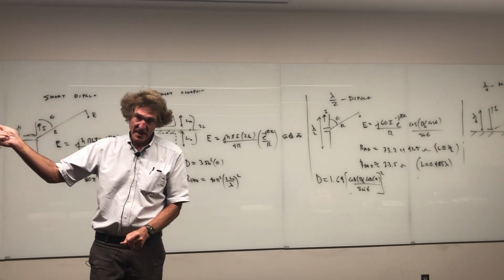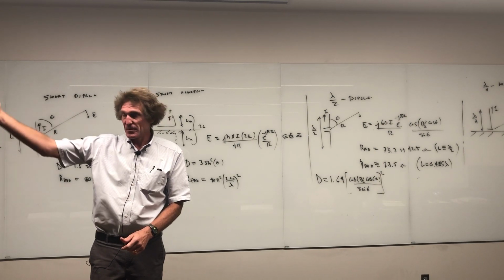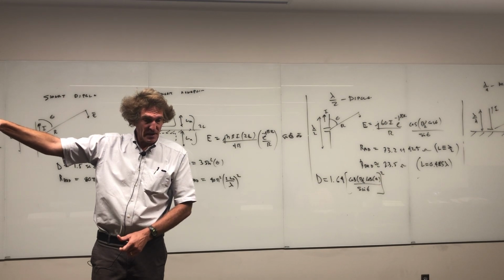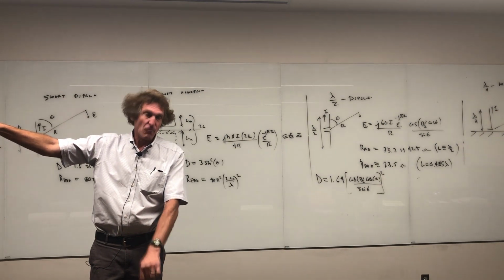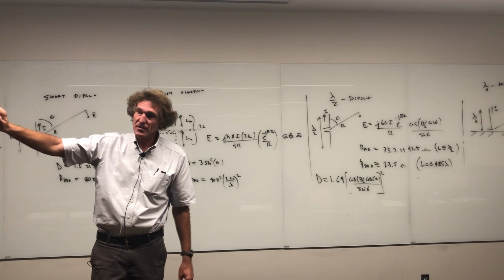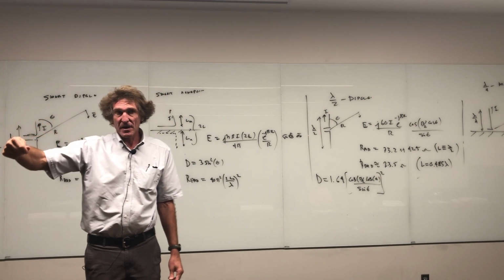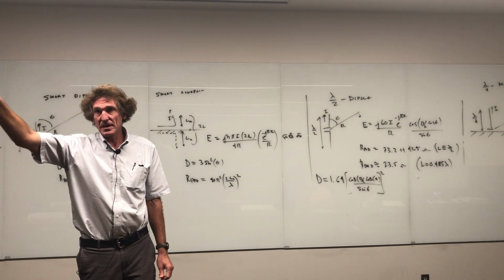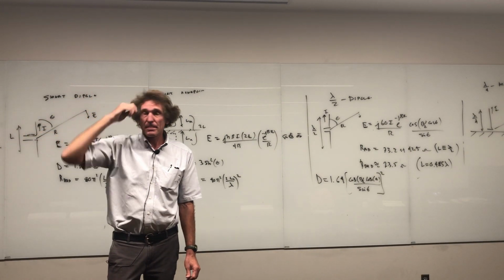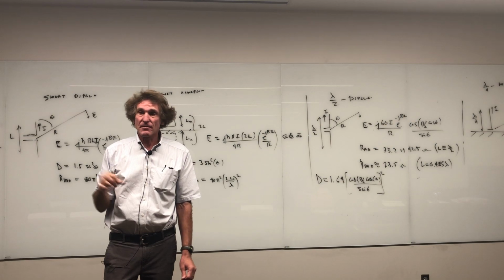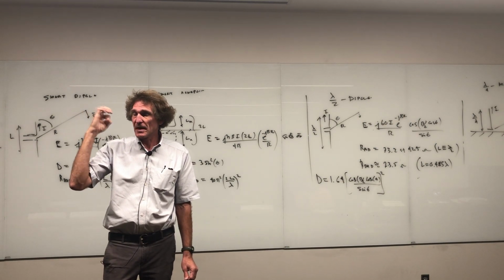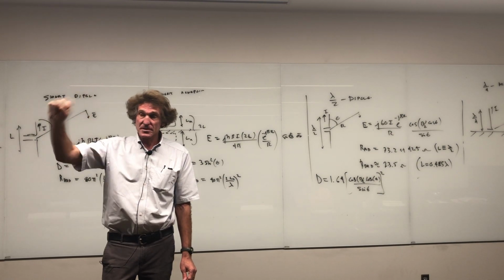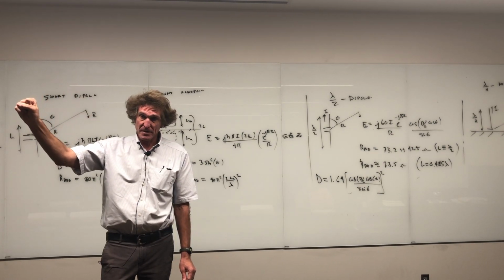And then you would take that with a special hook. If you had 10,000 volts on a capacitor and you needed that thing to be shorted out so you could do some work, then you would take that water resistor, put one end into ground, and go over there with a hook usually. On the other end, you tie a wire to it. Use a solid piece of grounding rod. Don't ever use this hollow aluminum, because when it starts shorting out, it can burst. It'll heat up fast and can blow up.